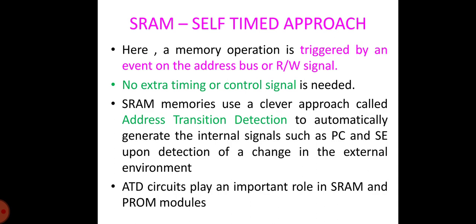A possible implementation of the ATD circuit can be shown, and it consists of a number of transition-triggered one-shots, one per input bit, connected to a pseudo-NMOS NOR configuration. A transition on any one of the input signals causes ATD to go low for a period TD. The resulting pulse acts as the main timing reference for the rest of the memory, which results in a huge fan-out. Adequate buffering is thus recommended. A more elaborate view of SRAM timing can be found in the case studies.